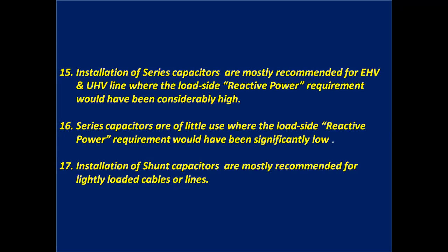Number 16, series capacitors are of little use where the load side reactive power requirement would be significantly low. Number 17, installation of shunt capacitors is mostly recommended for lightly loaded cables or lines.